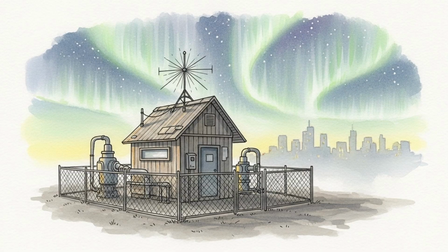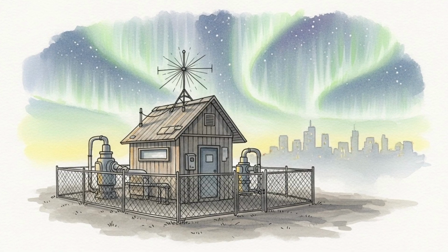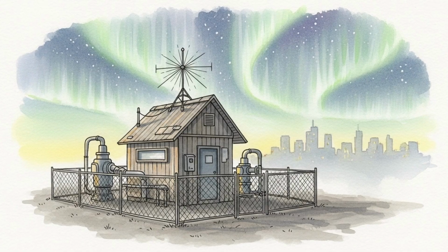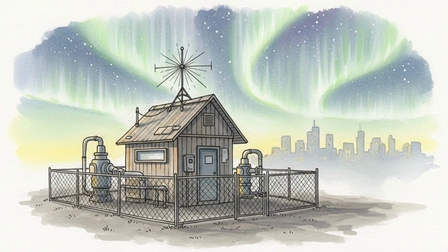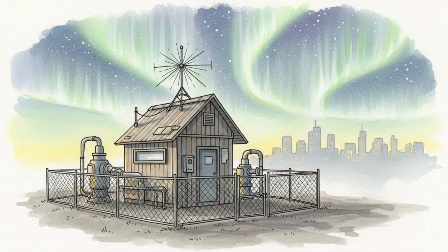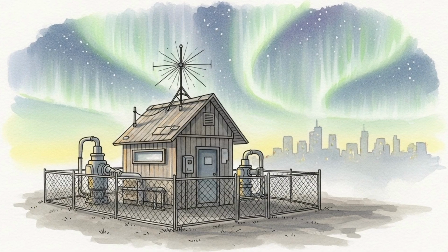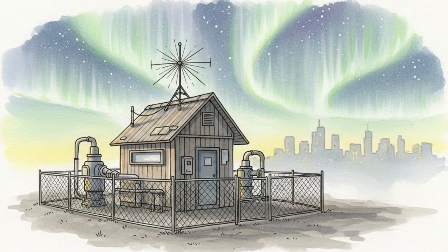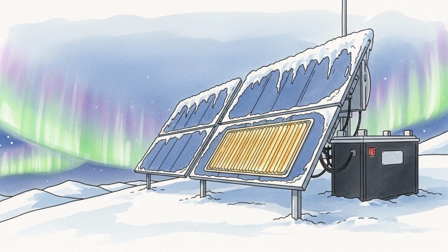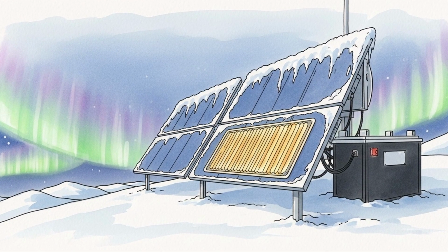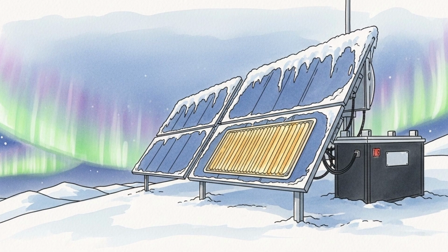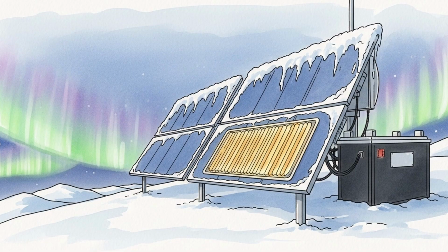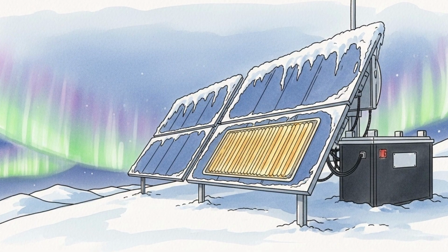Geographic distribution of impacts. High latitude regions see the largest ionospheric currents. Mid-latitude regions with conductive sedimentary basins and long coastlines can experience large ground electric fields. East-west lines are stressed when the induced field is east-west. North-south lines are stressed when the induced field is north-south. Urban areas with many shorter lines can be less exposed than regions that depend on a few very long backbones.